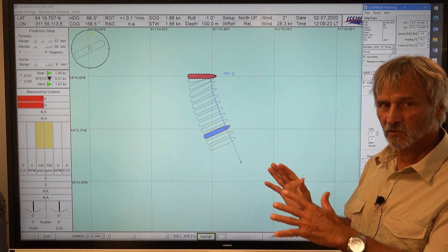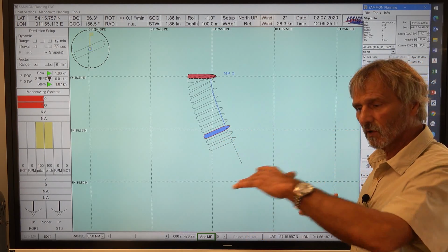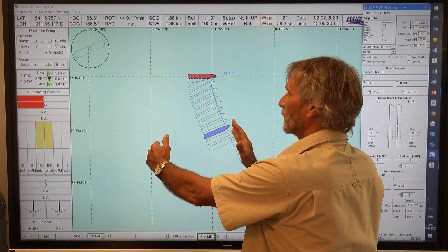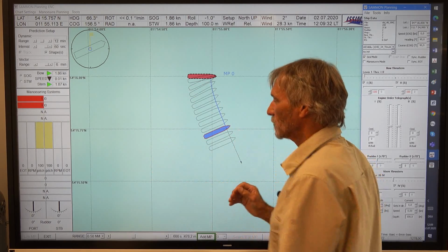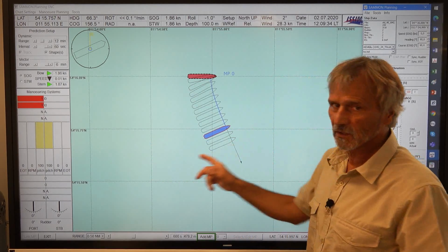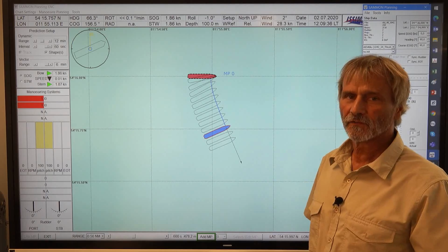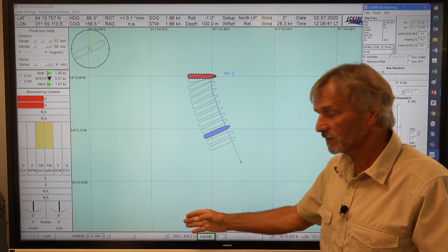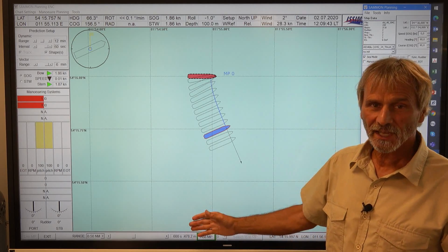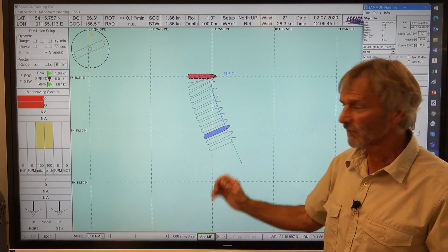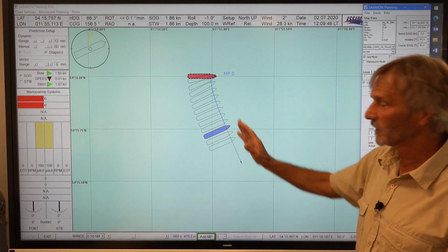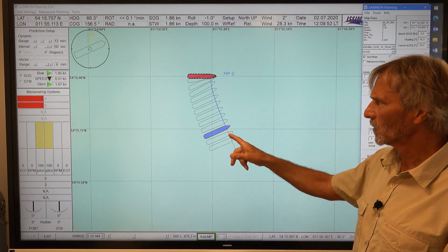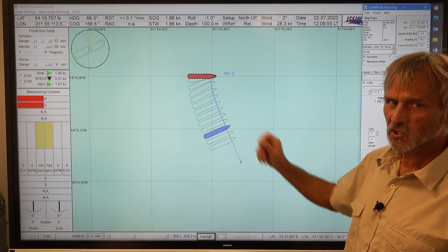By means of these two different options, only stern thruster, only bow thruster, we can change the drifting direction in a range of between 30 and 50 degrees. If you have an obstacle here at the lee shore, an island or whatsoever, which you should avoid, you can change your drifting direction very early. The question is, can we already achieve the maximum change of the drift direction?